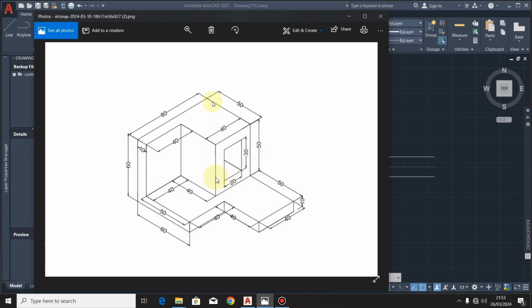So first we are going to start with the plan view. For the plan view, you imagine yourself viewing this object from the top. The views that you'll be seeing are this top view and also this bottom view. But then there are some parts of the object that you won't be seeing, like this rectangular hollow that goes through this part of the object. So let's get started and I'll show you exactly how you can come up with a plan view.